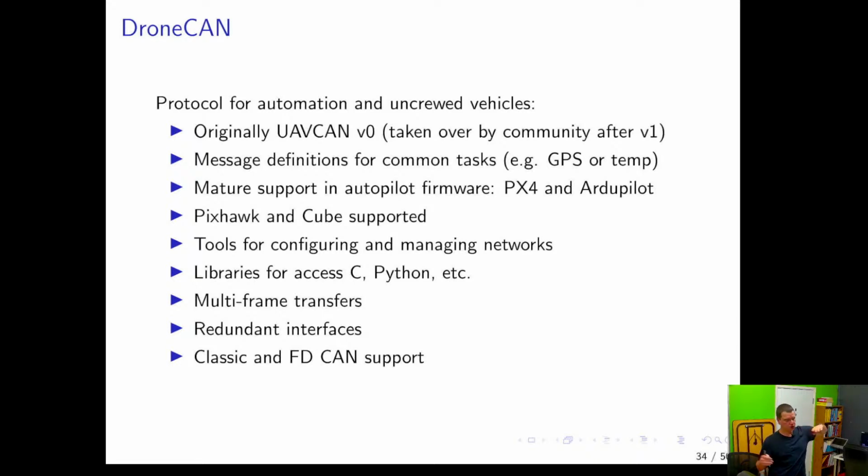So if you're building a big drone, there's two firmwares you would use. One of two, either PX4 or ArduPilot. This is for a big drone, like a big autonomous ag drone, that's not safety certified. ArduPilot is a practical, good firmware you can get in there and hack whatever you want in it. It works really well. It's tested, it flies perfectly.